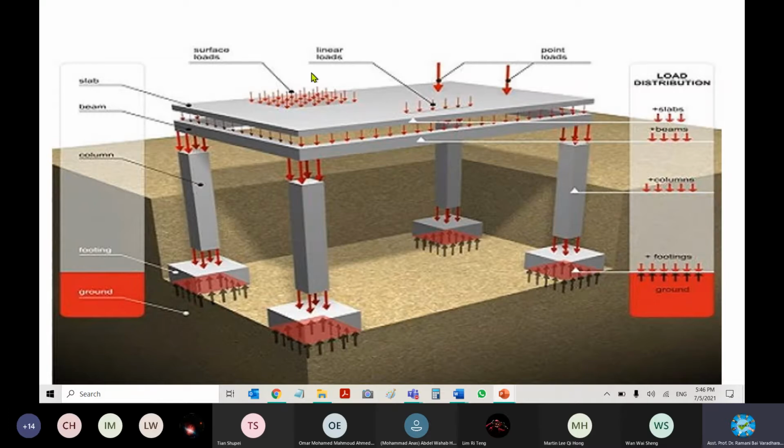But how do you calculate? By following the resultant, because they are all uniform, right? If the body is uniform and symmetric, the resultant is supposed to act at the middle, at the centroid of the body. I repeat, if the geometry is symmetric, what is symmetric? If you cut at any angle, it will leave two equal halves on both sides. If you cut here, a rectangle on both sides of same size. Cut here, also the same. Like that, the symmetry is maintained. Then the resultant will act at the centroid, the geometric center of the member.